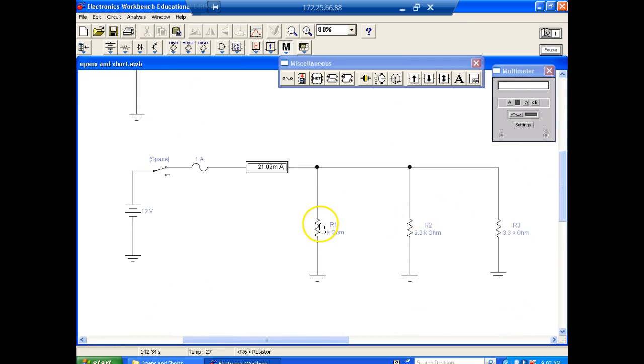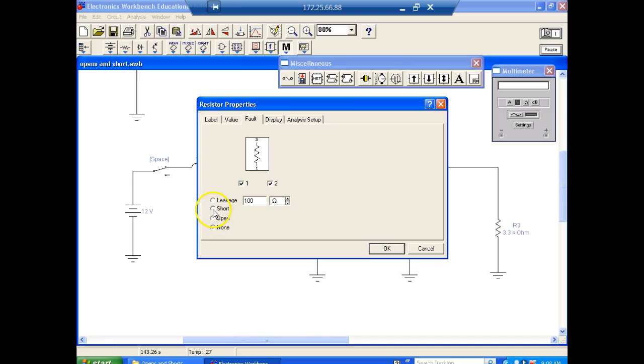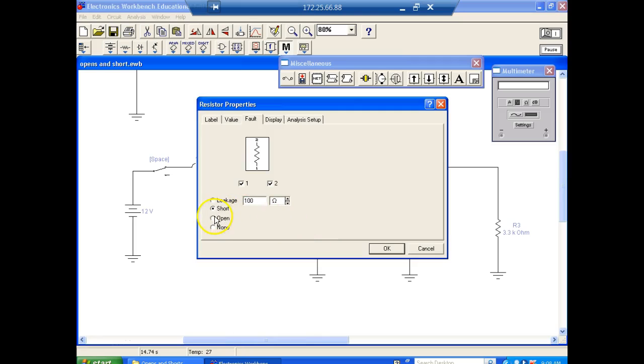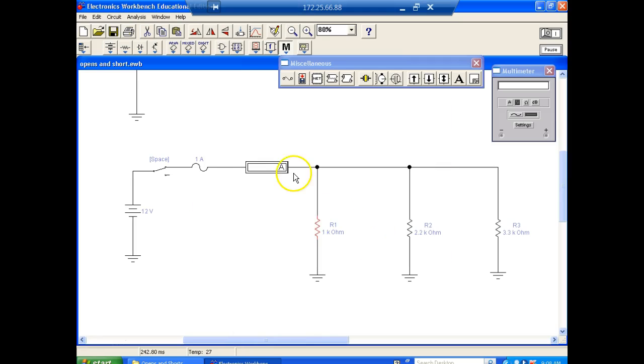But over here, we come over here, still got power on. Let's come up here and short this guy out. Now, as soon as I do this and turn it back on, what do we expect to see? Well, we expect the fuse to blow, because that's a short circuit, right? I just connected my source and my return together. So let's take out this. And it shows it okay, but it's not. But here's my fuse.